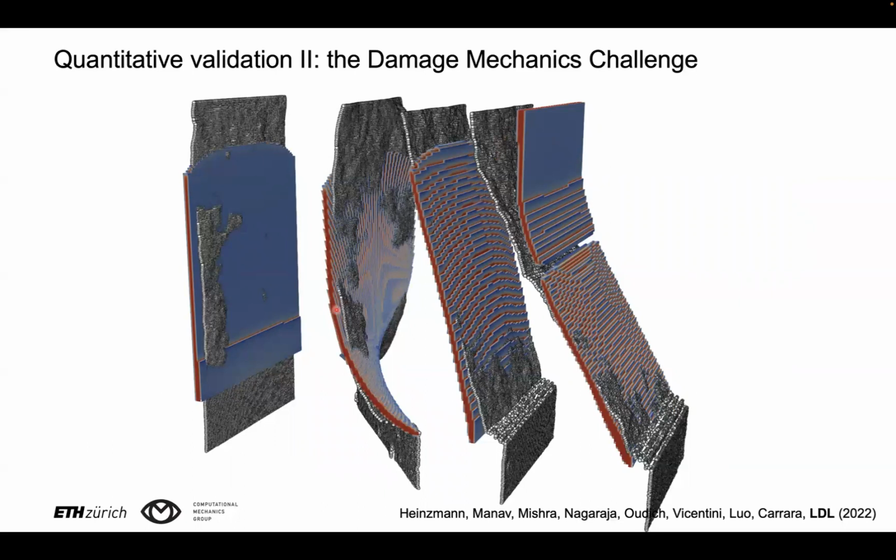But we were basically very satisfied by the possibility of calibrating the phase field model to such an agreement that we could reproduce these fracture surfaces to a very good level of quality. You can appreciate the 3D effect of twisting of the crack surface, which is generated by the offset and by the skewness of the initial notch.